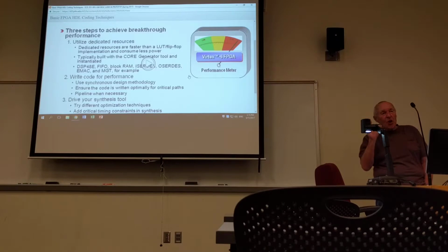And since it is hardware and not synthesized using CLBs out of the FPGA fabric, you wind up with a faster finite state machine if you implement it in block RAM. Part of the resources they weren't using.